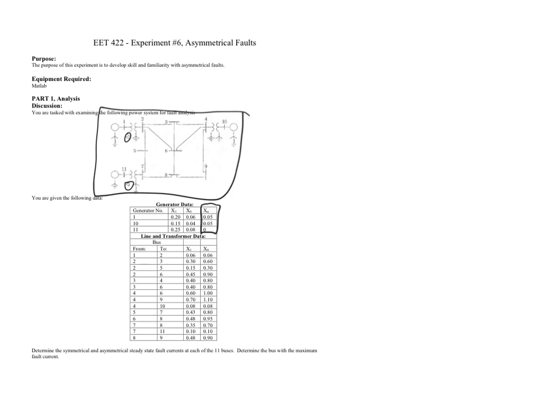We're going to draw the positive sequence diagram first, and the positive sequence diagram is the easiest one to draw. For positive sequence, we should only include our power supplies. All other ones should not have power supplies. So if you recall from our discussion during previous videos, we actually show a reference bus and what are the connections to this particular reference bus.